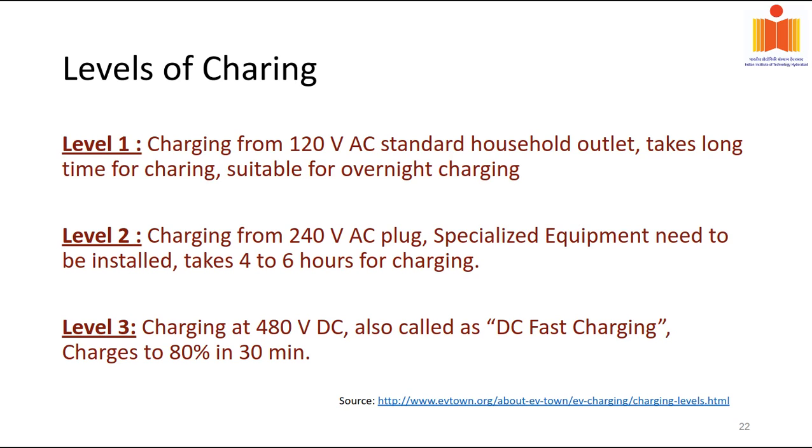And also in the literature we found that people are talking about levels of charging. So let us clarify this topic also. The first level is charging from a 120 volt AC standard household outlet. It takes a long time for charging and is suitable for overnight charging. If your charging demand is very high, it may take the entire night. It's not that this method cannot be used, but it has its limitations. Next, level 2 is charging from a 240 volt AC plug. Specialized equipment needs to be installed, and it takes 4 to 6 hours for charging. So instead of a 120 volt AC plug, you need a 240 volt AC plug.